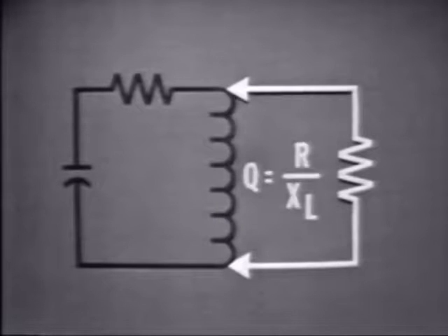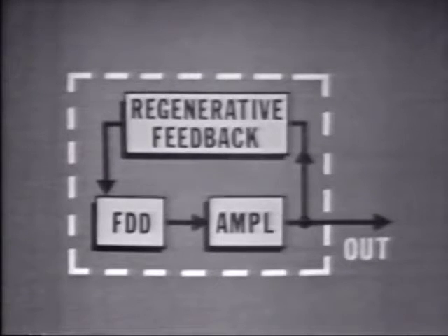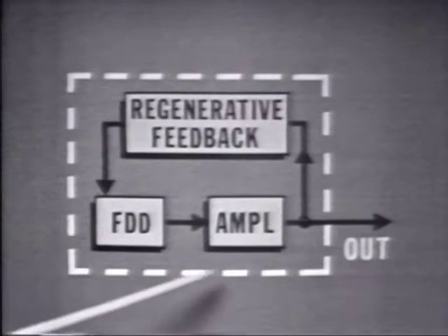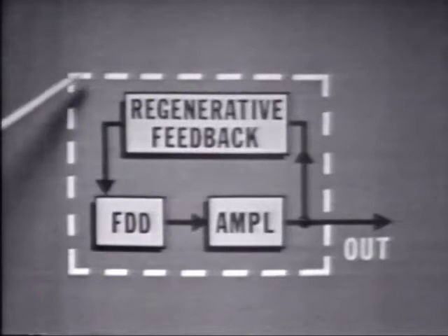However, there is another quality factor that concerns external circuit resistance, and in this case, the resistance should be high. In other words, the amplifier connected to the frequency determining device should offer maximum impedance to the tank. Even then, there will be some energy loss to the external load, which must be regained by increasing the feedback. Now, because loading and power surges can cause shifts in amplitude and frequency, the oscillator stage is usually isolated from the rest of the equipment by special amplifiers or other circuits.